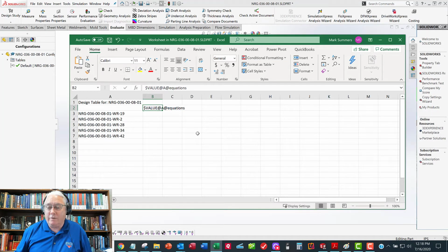All right, we're going to shift and we're going to arrow to the right. We're going to do this 4 times. I'm going to do a Control D to roll it. Whoops. What am I doing wrong here? 1, 2, 3, 4. Not Control D. Excuse me. Control R. Roll it to the right. All right, there's A. I'm going to come over here and change this to capital B.